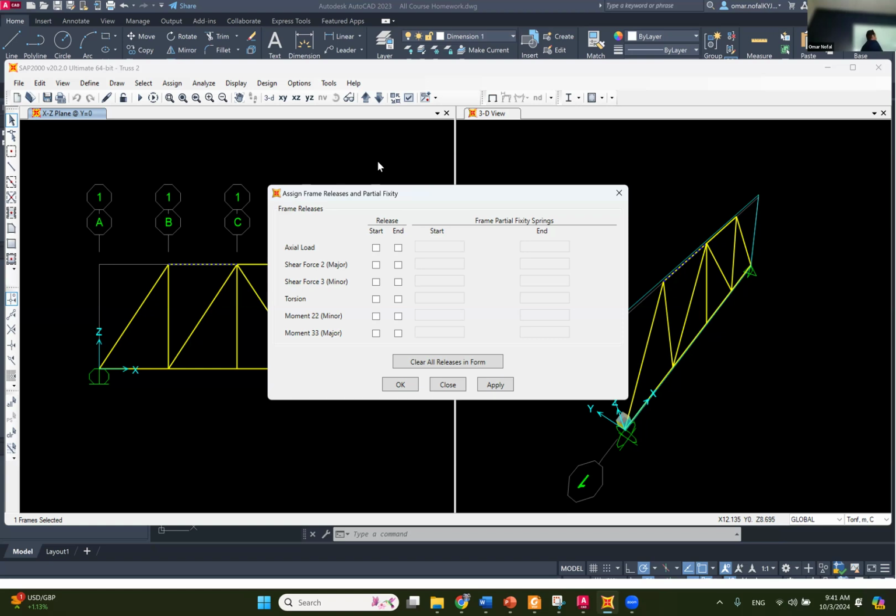But let's say that we have a rotational spring K equal to 200 ton meter per meter. Okay, that's a rotational spring. That's how I figure out if my unit is true or not. So K is going to be equal to M over delta, right? Not delta, theta. So this unit is not right. It's going to be radian, because I know this unit is ton meter and this is radian. Okay. All right. So this is the stiffness of this rotational spring, 200.